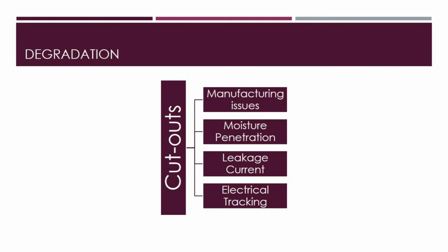Damaged insulators are the equipment's first signs of failure. High electric fields may develop from chips or cracks throughout the uneven area. Small leakage currents from the conductor to the pole, bracket, or crossarm would result from these electric fields. And when the cutout is activated and a face-to-face voltage is present across the insulator, leakage currents can form. Leakage currents ionize the air and heat the porcelain, causing possible arcing and dielectric breakdown.